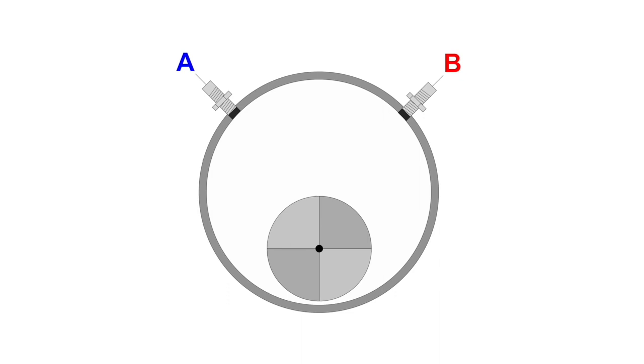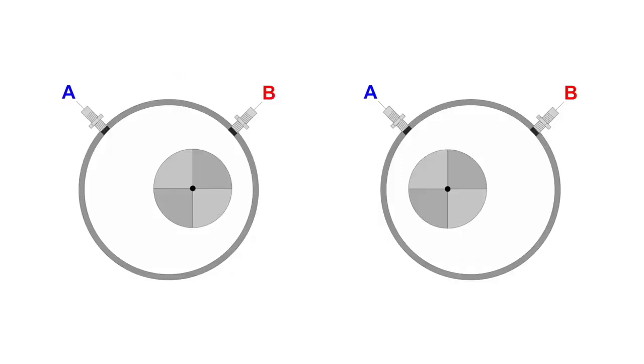When we use two proximity sensors, then we can display the position of shaft in bearing. This is 0 machine speed, less than 100 RPM usually. Shaft is assumed to be at the bottom. Normal positions on nominal speed. The position corresponds to the direction of rotation. The position tells nothing about vibrations. It is just the DC part of signal.